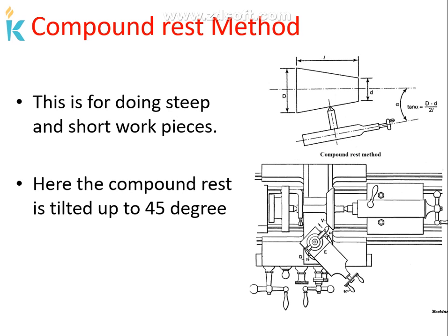Long tapers can be easily produced in this method. Then threads can be produced on the taper surface. Accurate tapers can be easily obtained in a single setting. So we can produce accurate tapers. The required angle of taper we obtain in the compound rest method. Then skilled labor is not necessary for this method.